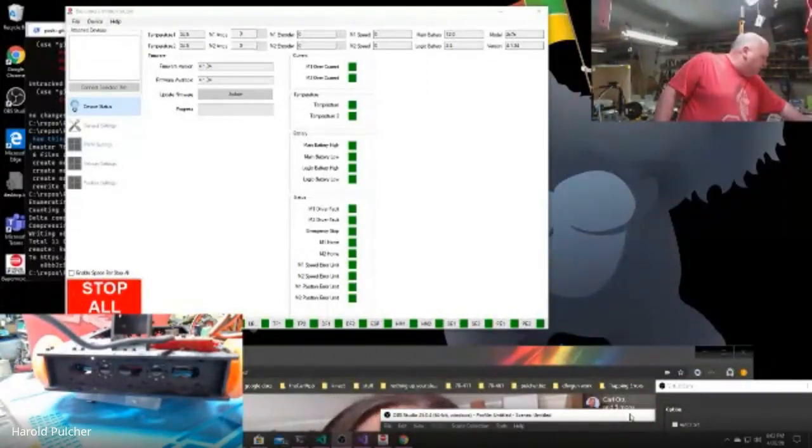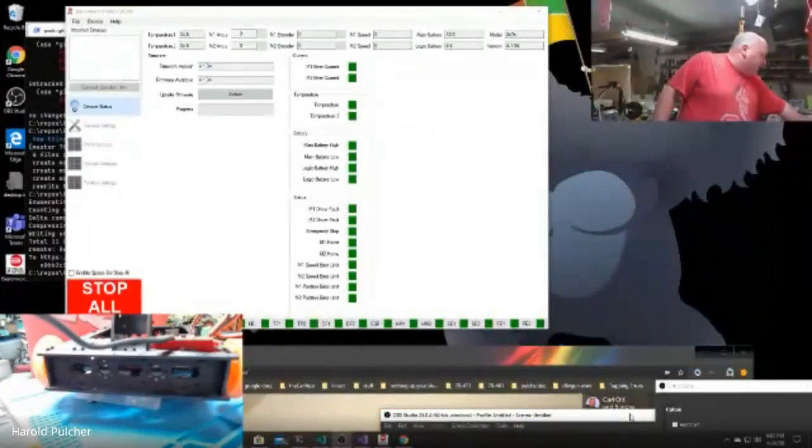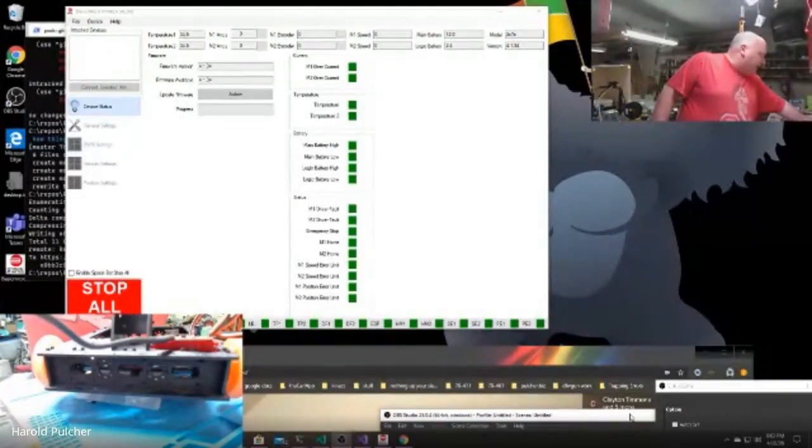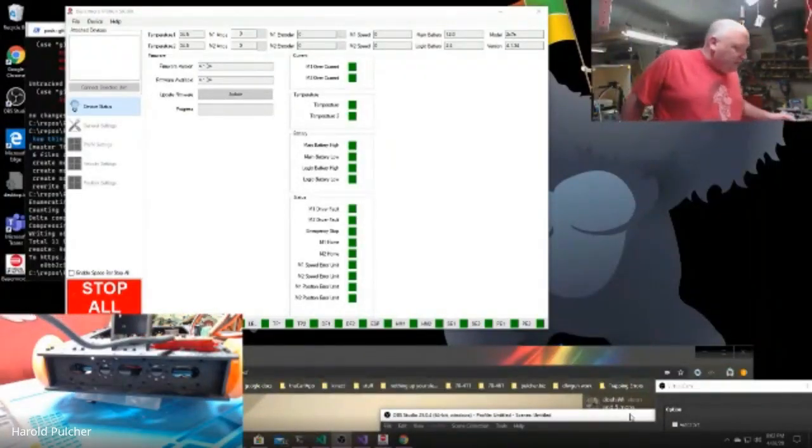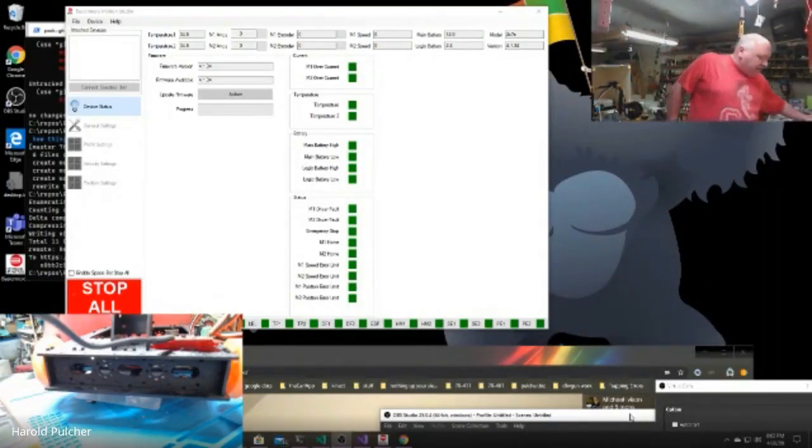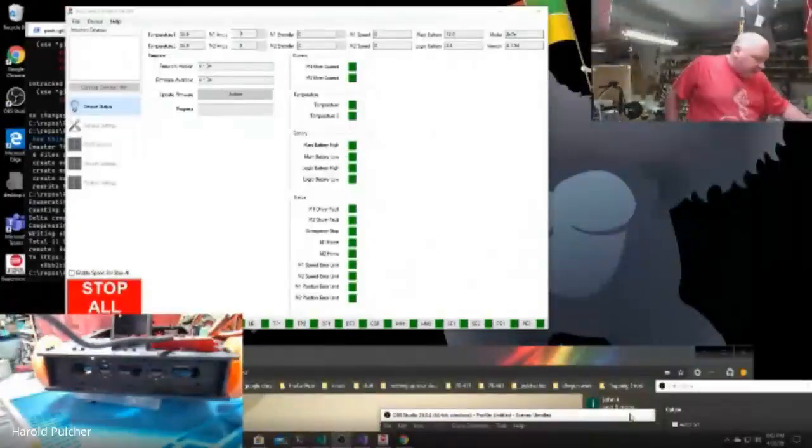You guys smell something burning? Yeah. You guys are funny. Oh, my power supply went into constant current mode, not constant voltage mode, and so now I don't have enough juice to do the thing. Hold on. Sometimes that can mean a short. I hope that's not the case.